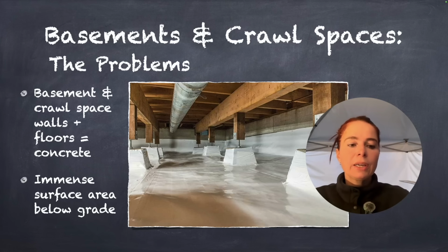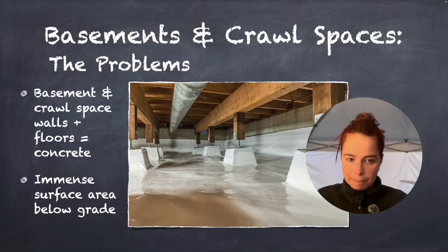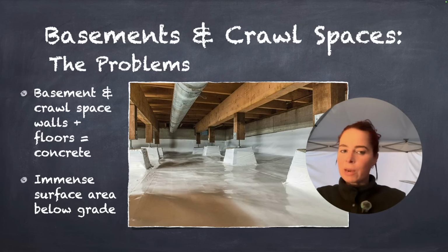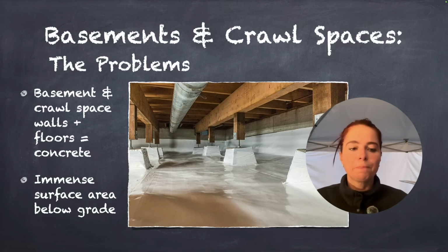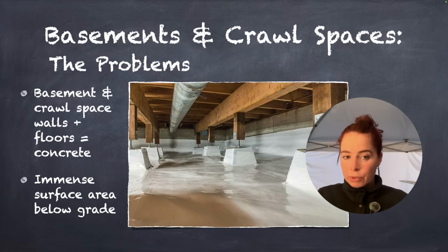So again, you've got all that concrete, which again is porous, full of those microscopic pores. It'll wick water inward and upward by that capillary action. It's the same way that a paper towel will soak water up. And a basement slab or wall that is in contact with the ground is going to be drawing in moisture. 100% that's going to happen.